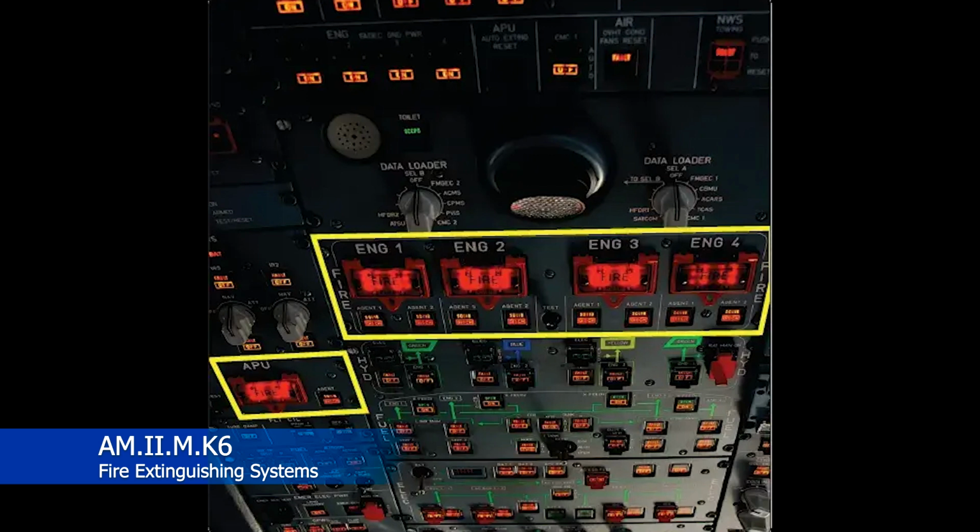On the overhead panel, you'll have fire bottle switches for engine 1, engine 2, engine 3, engine 4, so obviously it's a 747, and then the APU off to the side. If you get a fire warning, you would lift up the little guard that covers that switch, and then press the switch, and that'll fire the squib.